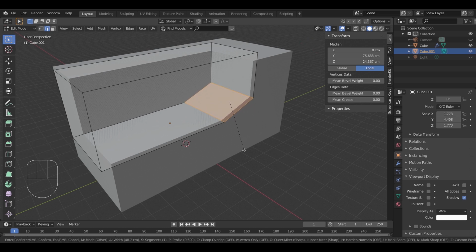One thing you need to keep in mind: if you want to add modifiers, textures or apply some of the tools like Inset and Bevel to an object, and the object has been transformed with the Rotate or Scale tool, you need to apply the transformation first before you add those modifiers or textures. Otherwise it won't work right, and you will end up wondering what the problem is.